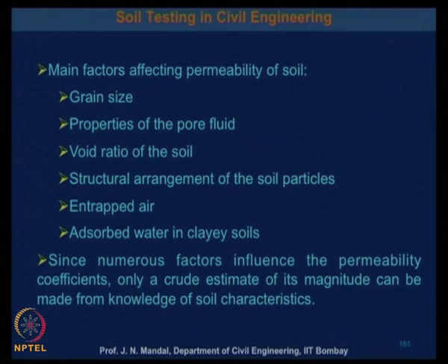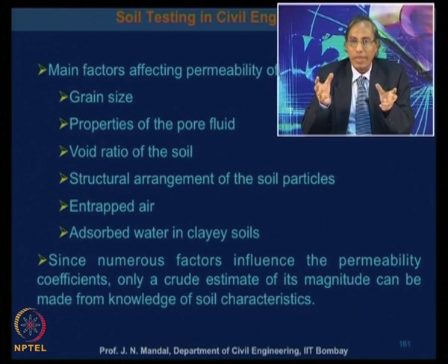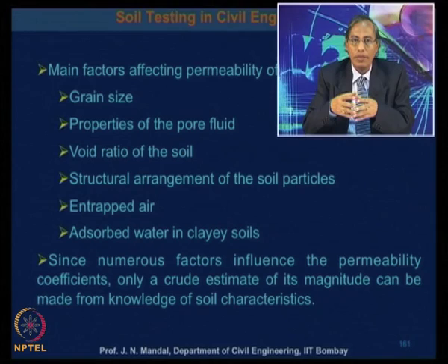There are many factors affecting the coefficient of permeability of the soil. It depends on the grain size of the soil, the property of the pore fluid, the void ratio of the soil, the structural arrangement of the soil particles, then entrapped air, then adsorbed water in clay soil.